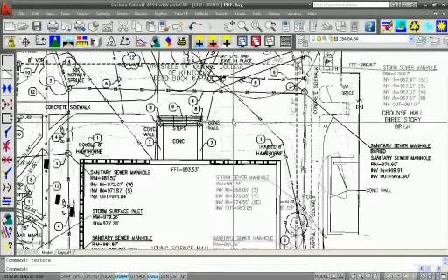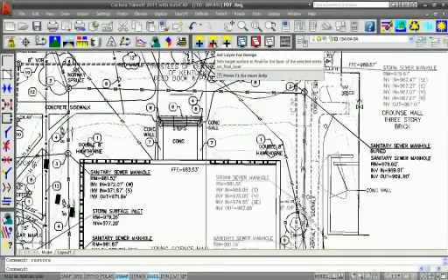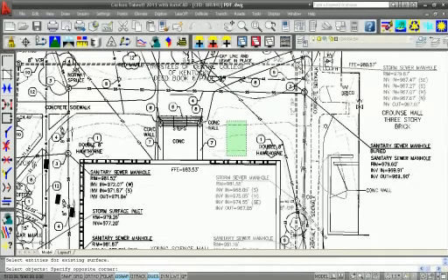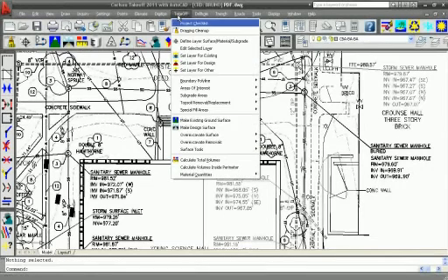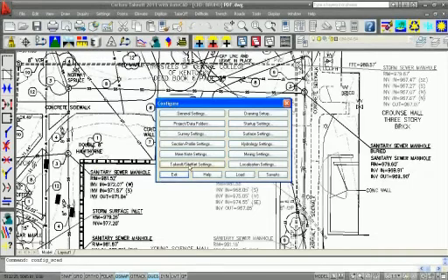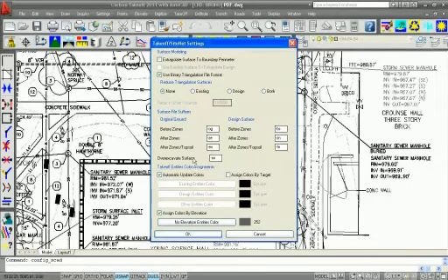So I can easily set those. I can say set layer for existing. These look like existing contours. And I am just going to change one setting that we have in Takeoff first, and that is under Carlson Configure, Takeoff, SiteNet settings.